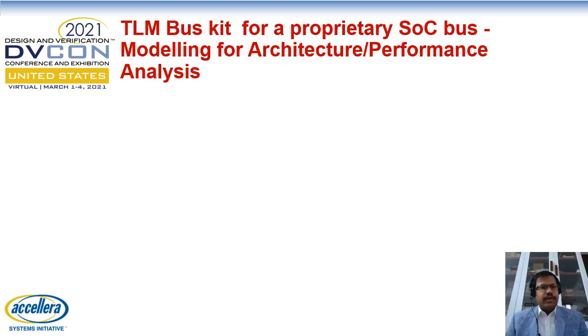Moving on, we are going to look at the TLM bus kit for proprietary SoC bus modeling for architecture or performance analysis. What is the need for such a bus kit? When we are doing architecture analysis, we are early in the cycle and we are yet to commit to a certain ISA or a certain memory bus. We want to select the right bus which satisfies our bandwidth, latency and power requirements. So there are two concerns here.